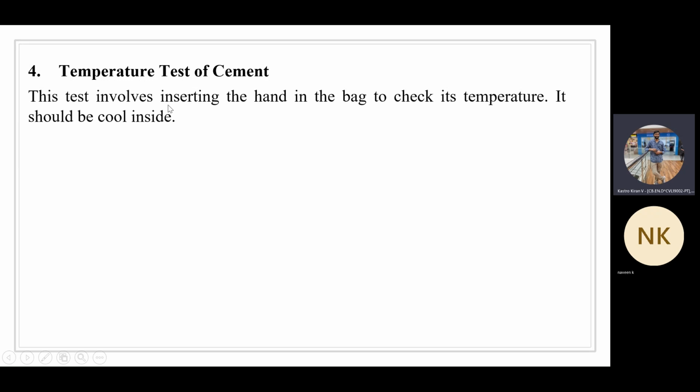You can see here, this test involves inserting the hand into the cement bag to check its temperature. As soon as you dip the hand into the cement bag, you should feel coolness inside the cement bag. If you feel anything other than coolness, that cement is also not a good cement.